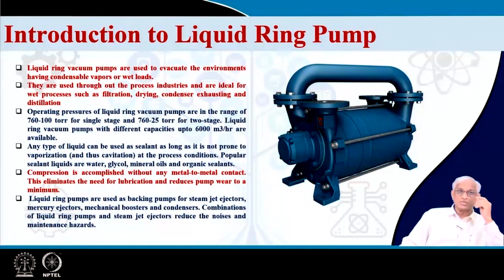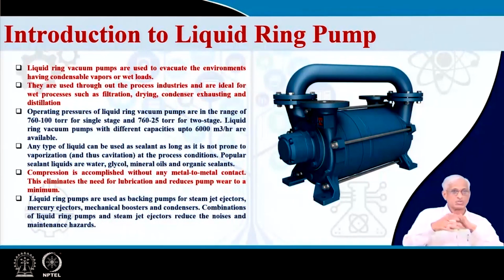Its vapor pressure you have to take into consideration, its viscosity and its boiling point, etc. Because you have to take care of several issues like cavitation and even the power of the motor, because it is going to push water column. It is not like a gas type of thing. So, a little bit more thrust is required. So, the motor power requirement is also a little high.